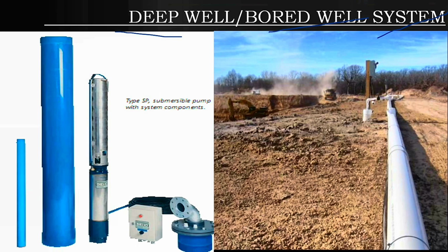Okay, so the next one is the deep well point or bore well system. Some of the students are very lazy. They think of a shortcut: sir, if I need to go up to 14 or 15 meters, then why should I choose different stages and work in different stages? I look for alternatives. For that we have an alternative, which is represented as the deep well point system or bore well system.